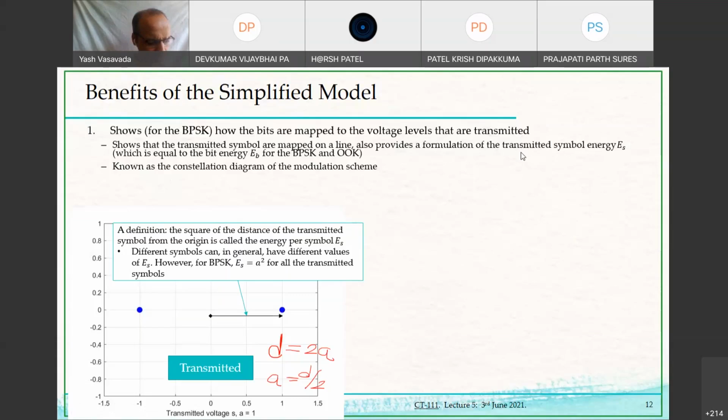Because we are working on minimum distance decoder. Exactly. We are working on minimum distance decoder. Very good. And so a lot of the times we are going to be focused on what is going to be the decision rule, or what is going to be the performance of my decoder. So decision rule is always going to be dictated by minimum distance between 2 points. And so it's good that we start thinking about this constellation diagram in terms of what is the distance separation, Euclidean distance separation between the 2 points.